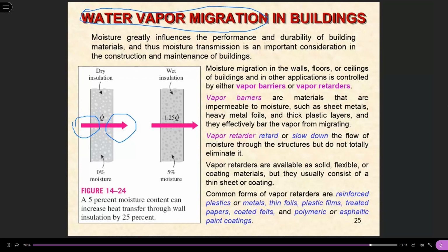Second, in a very cold climate, the moisture in the structure can cause freezing. In other words, when moisture freezes, it expands, and it damages the structure of the building. In fact, that is one of the problems in test 1. So in this lecture, because of time, we're not going to talk about the calculations. You should have this common sense that for that reason we use vapor retarders.